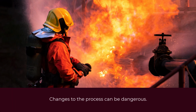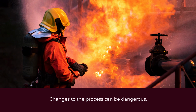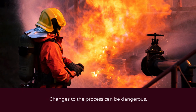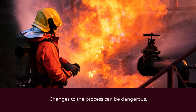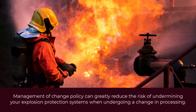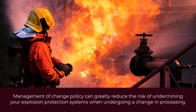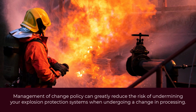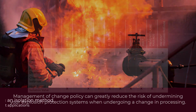Changes to the process can significantly impact the effectiveness of the explosion isolation method. Some factors that could compromise the explosion isolation system include a change in the equipment, product, or operating temperature or pressure, process flow, or airflow. It is critical to develop and adhere to a robust management of change policy for assessing alterations to the process or product that potentially could undermine the ability of the explosion isolation method to perform as originally designed.